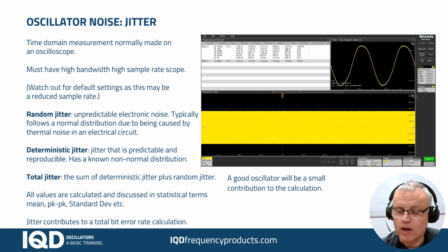What I have learned from this is that you need to be careful when you adjust any setting on the oscilloscope. Very often the bandwidth jumps back to some default value, and you have to manually turn the sample rate back up to the maximum. So just a little tip there when you're playing with this equipment. We found that to be the case in most of our scopes.